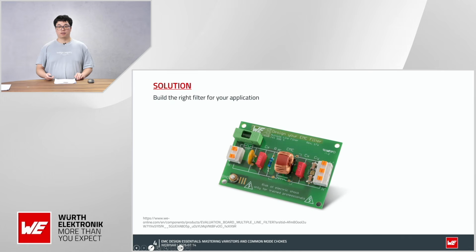Okay, so here you can find an example of the EMC filter used to attenuate the electromagnetic noise. The circuit is composed of a fuse holder, a varistor, a discharge resistor, a common mode choke, and the X and Y capacitors. Each component has its own function. For example, the varistor is used to attenuate the overvoltage transient noise, and the common mode choke is used to attenuate the common mode noise. In the next slides, we will go deeper and explain the detailed characteristics of each noise and the corresponding protection devices. Due to the time limit, we are not able to present all the components in this webinar. We are mainly focused on overvoltage signal attenuation and common mode noise attenuation.